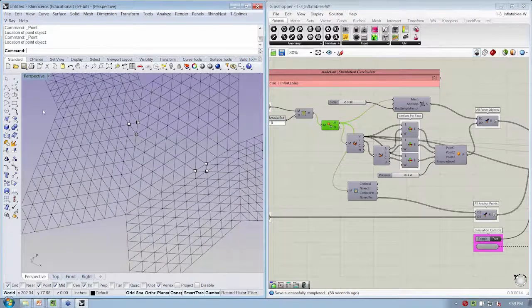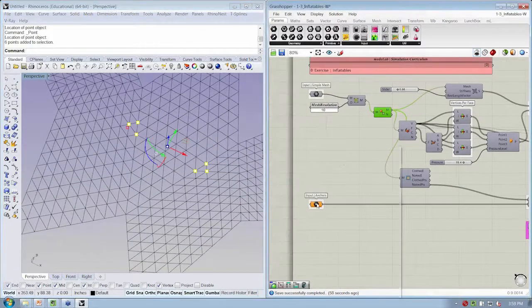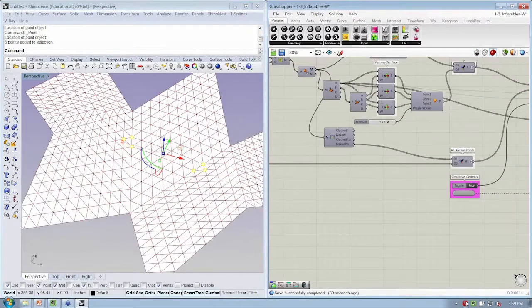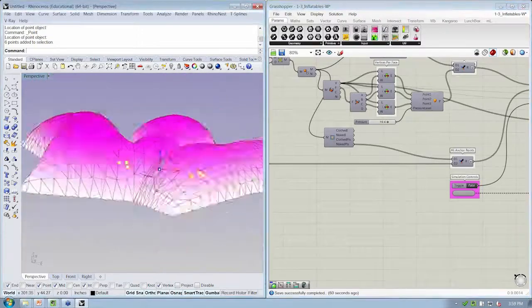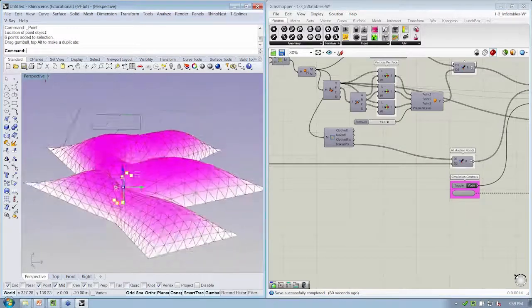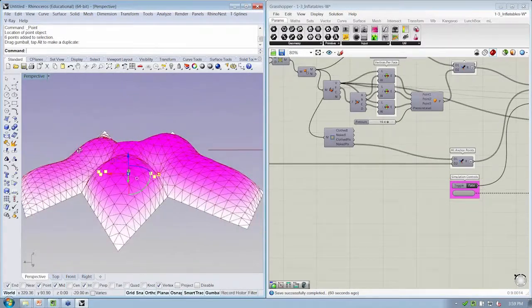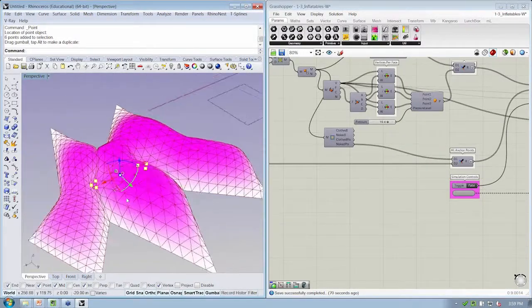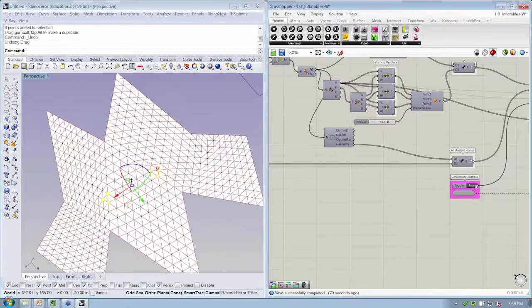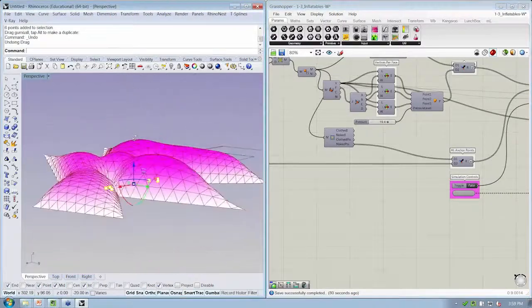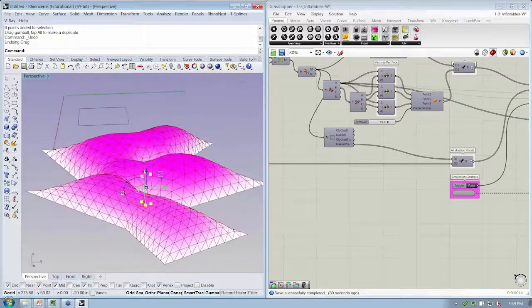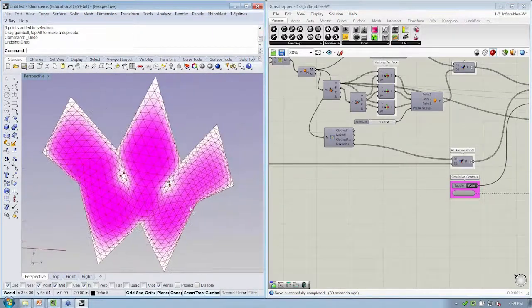I'll try a two-column system this time. And then bring those points back into Grasshopper. Let my simulation go again. Now I have those points that I can start to manipulate. Now, if I start to stretch them out of the XY or move them at all, I need to make them be back in their original position before I run my simulation again. Otherwise, they'll be lost as anchors because they won't be touching another point within the simulation. That's a good question.